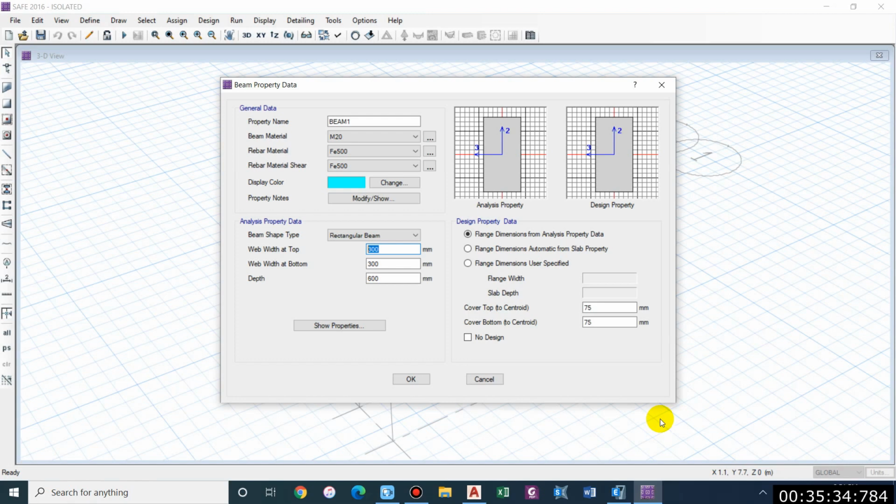So we are just considering at least the size of the beam equal to the width of column. It can be greater than the size of the column as well, depending upon the requirement. So for now 300 as we are considering a rectangular beam, so 300 by 300. Depth, let us take as equal to depth of footing, so 400 mm. Clear cover to center 50, 50, okay.